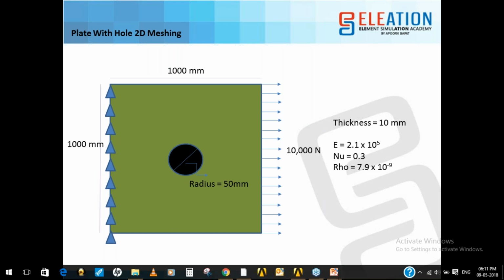The theory we have learned during the 2D theory, those parameters or concepts regarding how you need to mesh, if you are using a quad element, why it is good to use a quad element, and how far away from the actual results your tri elements are going to give. All these things we will come to know at the end of this session.